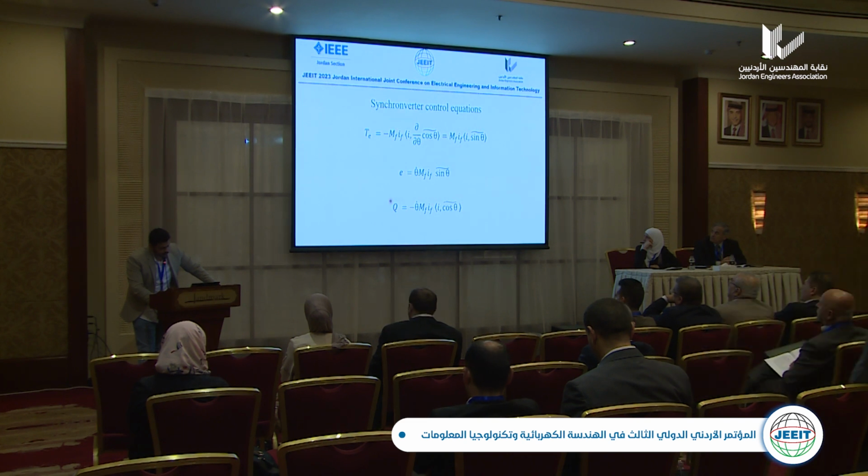And the last equation is the reactive power equation, Q equals minus omega MFIF multiplied by the dot product, or inner product, of vector I and cosine tilde of theta.